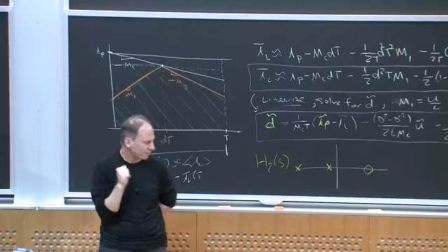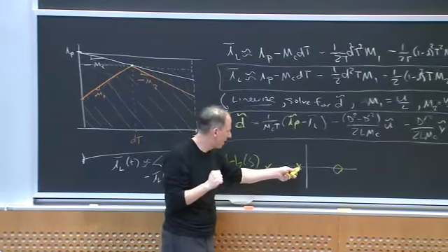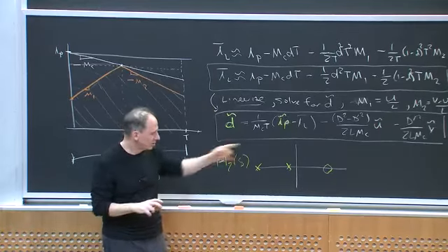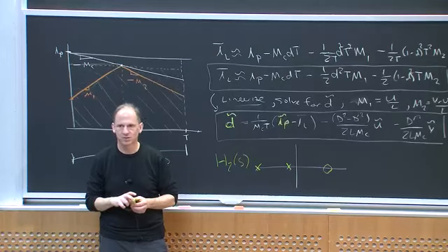So it's not that I have a first-order system. There is a second pole here, it's just dominated by this low frequency pole. And that's a much easier thing to control. Any questions about that?